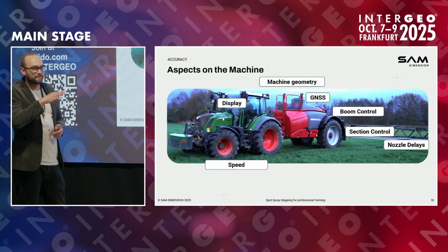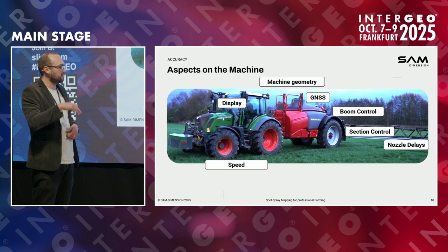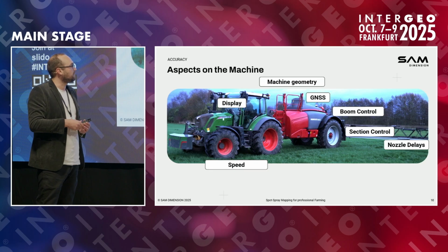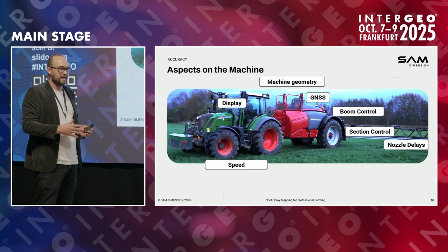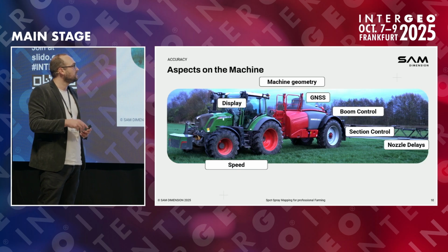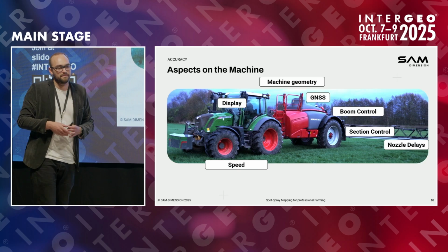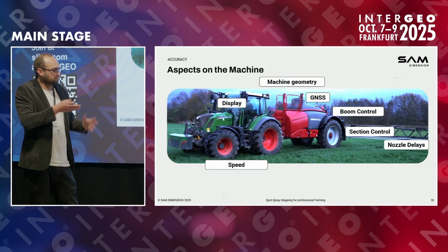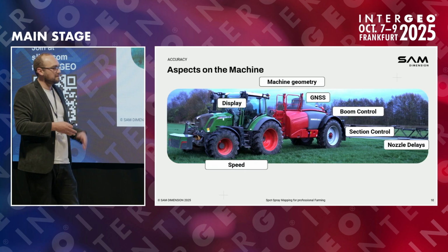Because the actual accuracy of the sprayer is the more challenging thing than our detection on the ground. We usually buffer every point by some 60 centimeters, not because we are not sure that the point is there, but because we are not sure if the farmer calibrated the system, the tractor, this big 3D printer basically, correctly.